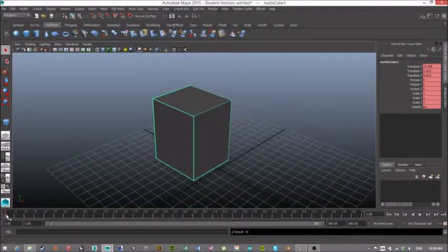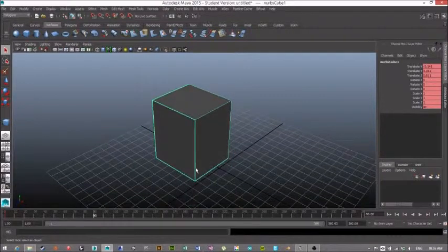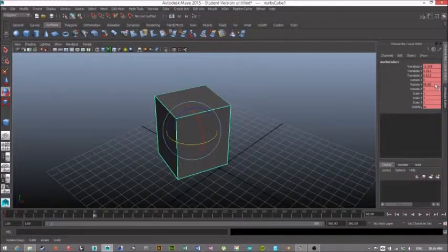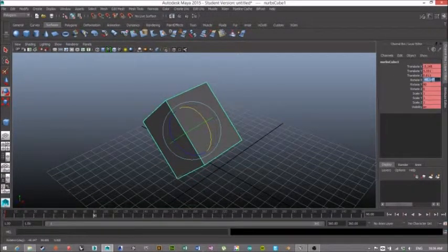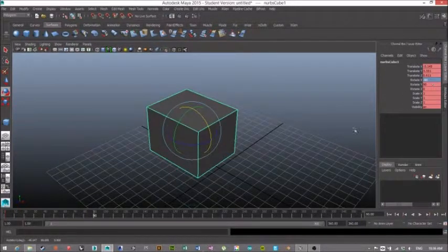Now what you do, and this sequence is very important in keyframing, is move the time slider to the frame that you want to be dealing with first. So we'll say 90. Then we will rotate our box 90 degrees in that direction, and we'll rotate it -90 in this direction. Okay, so now we've got our geometry being transformed a little bit. It's selected, our time slider is where we want it, and we just hit S again. This little red strike shows up. Great. Now if we scrub through here,